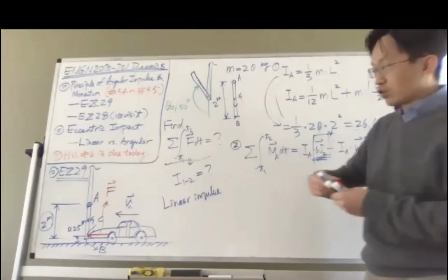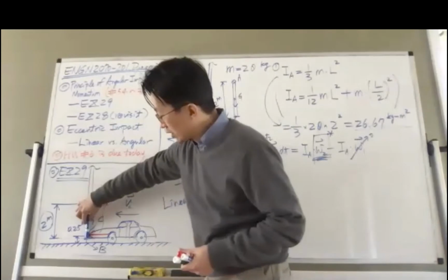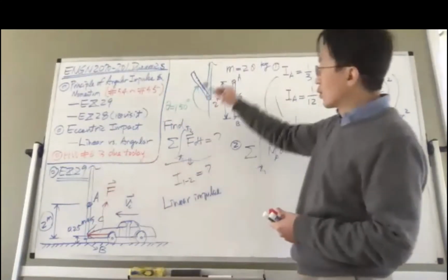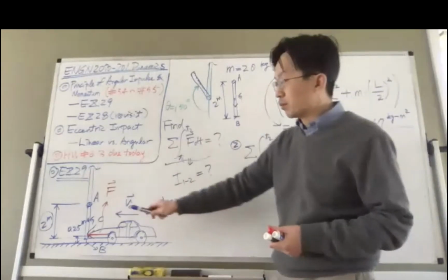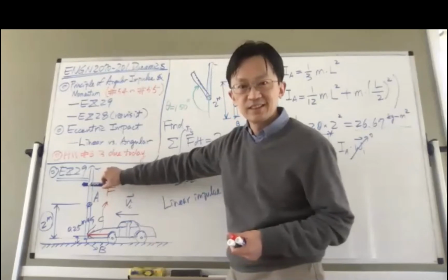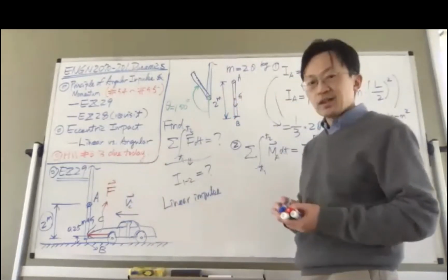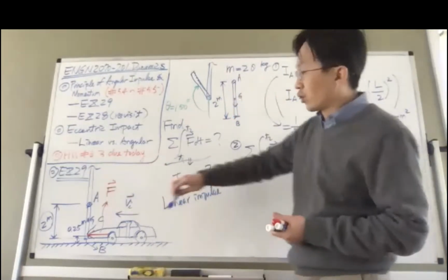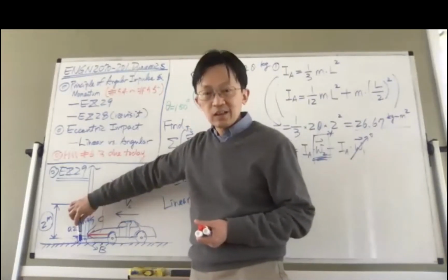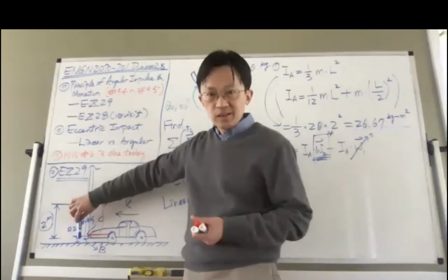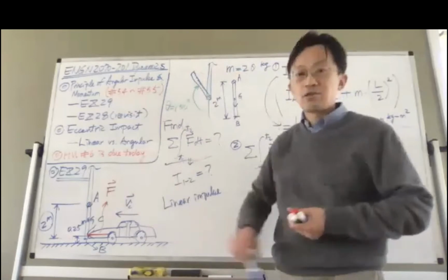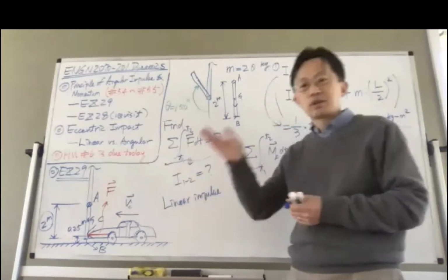Because in order for the door to move from the vertical position and swing up to 150 degrees, you notice that the center of gravity has been moved from this position to somewhere here, correct? What does that tell you? That tells you that in order for the door to move, it must use its kinetic energy to consume potential energy. Because when the thing goes up, you will have to convert kinetic energy into potential energy.